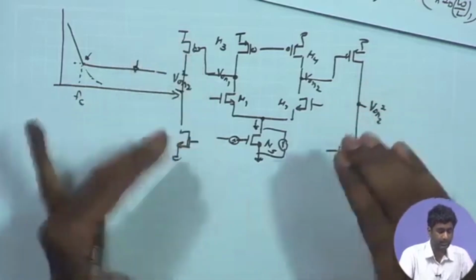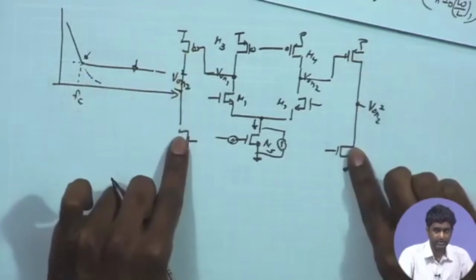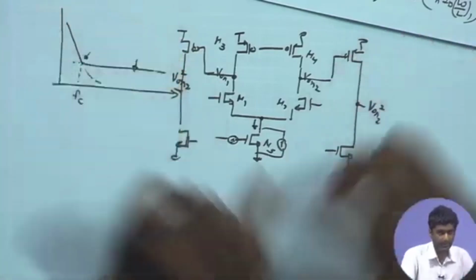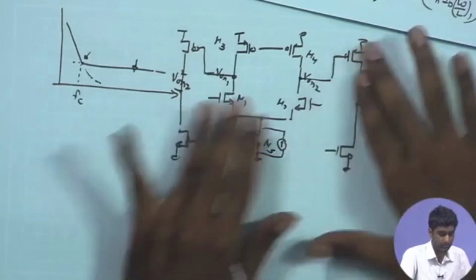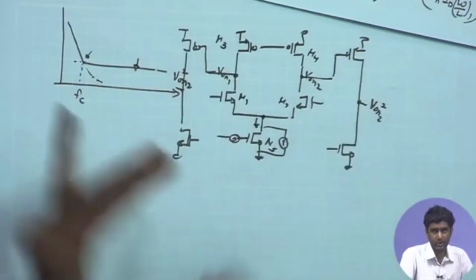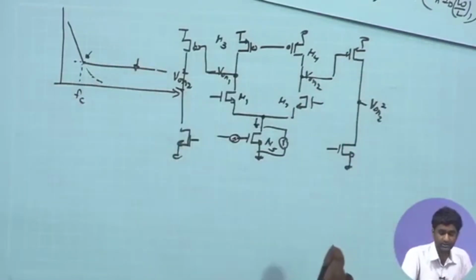We can certainly take advantage of this relaxation by having more relaxed constraints on W/L and bias current. So, we are mostly focusing on the first stage for the minimization of the 1/f noise through the technique which we are going to discuss next.